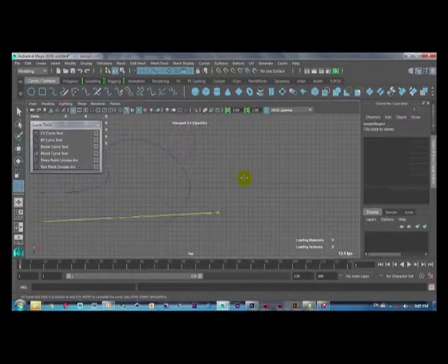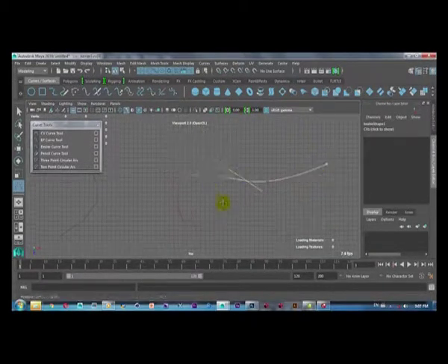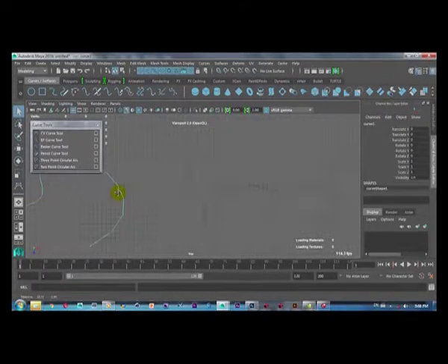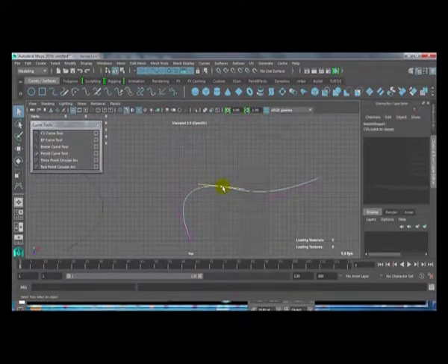An EP or an edit point is a point that lies on the curve or surface. Use the EP curve tool to place points one at a time. The curve is created to interpolate them with one span between each edit point. Both commands create the same type of curve, but the way you draw with them is different. You will mostly use the EP curve as it runs through the points you specify. In most cases, that is the most convenient way to draw a curve.